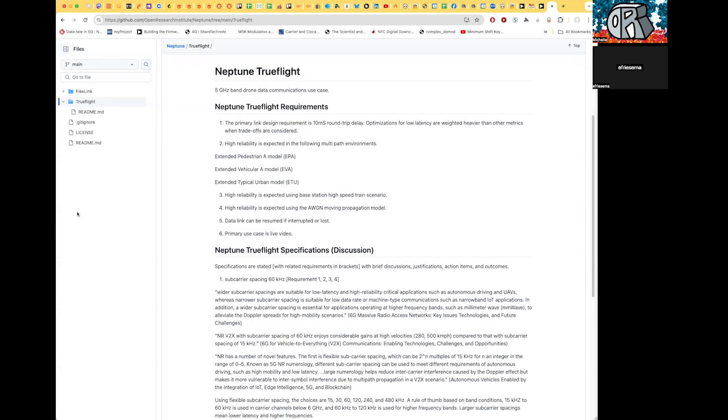So I was looking at round trip delay as a real round trip delay, as if it was what is delivered to the operator. No, that's not really true. It's unlike cellular telephony where your ear is actually hearing the round trip delay pretty much. And if there's other delays in the equipment, and they tend to be larger than other consumer electronics, then we need to actually specify both. Like here's our delivered RF delay, and here's our assumptions about the round trip delay. We need to actually work that into the requirements somehow.